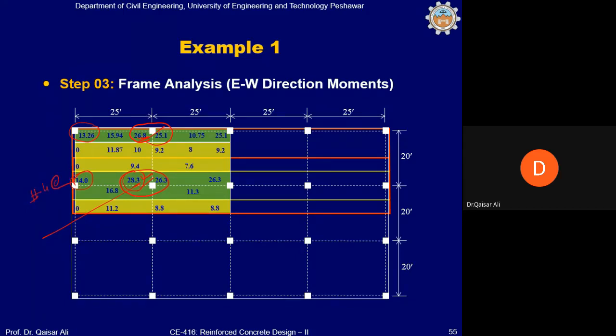So we can say that number 4 at the rate of 8 inch or 9 inch center to center will be enough for this. So in this manner, for both the bending moments along the north-south and east-west direction, area of steel can be calculated, and then final spacing recommendations can be done by grouping the area of steel so that spacing variation is kept as minimum as possible.